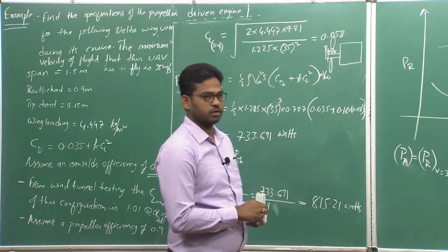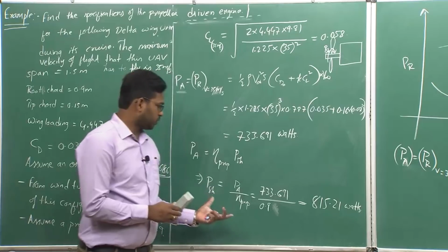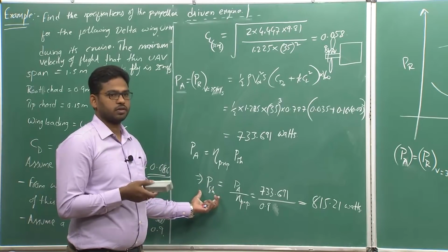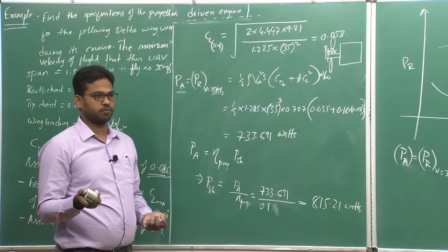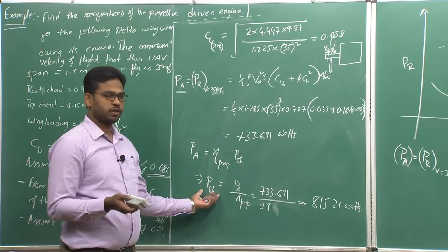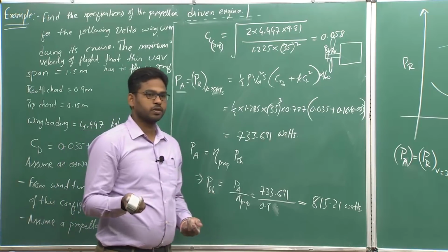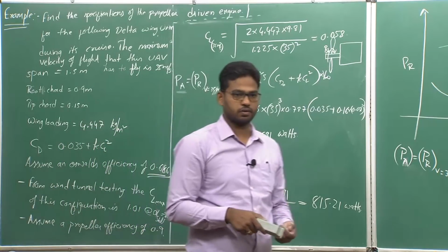35 meters per second. But ideally this should not be at the peak power of the IC engine, or whatever power plant that you select. You need to get this power at about 50% of what it is rated for.